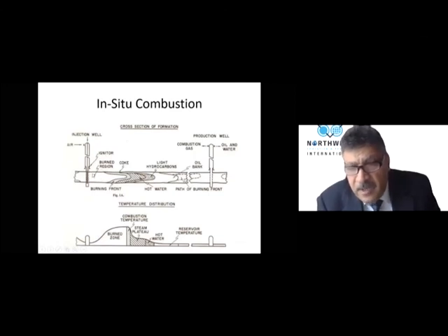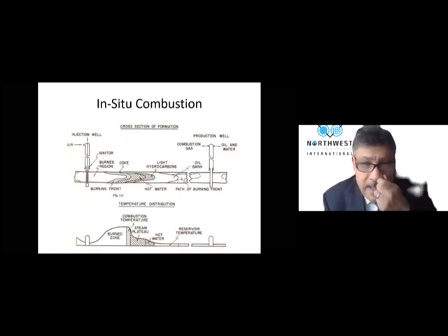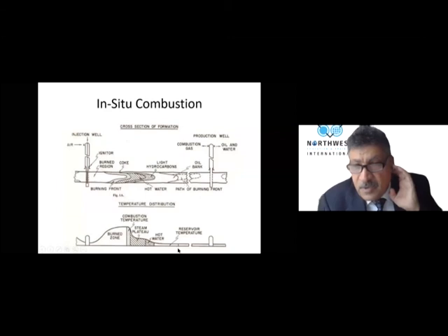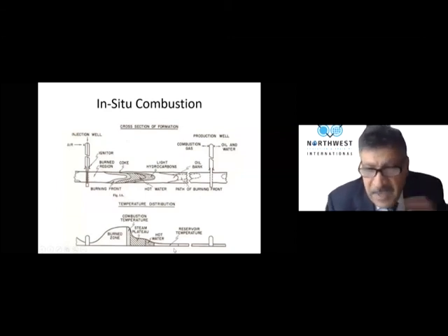So I'm burning the oil inside the rocks, and that hot burning makes the oil much less viscous. The air injection is a continuous injection by a compressor, builds up the pressure and pushes the oil from the injector to the producer. That's the basic idea.